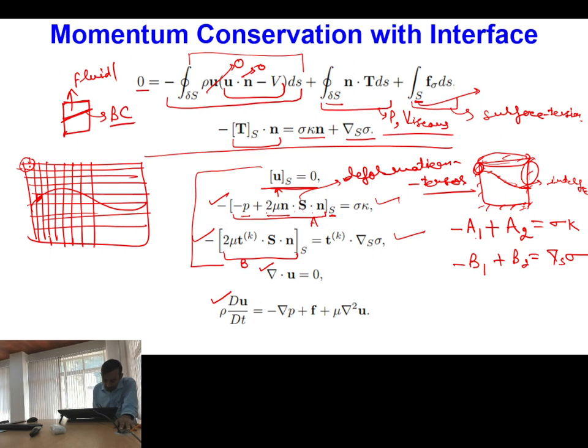Similarly, for fluid 2 you can solve this entire portion, but whenever you come to this cell, you will be solving only this much portion, and then at this point also you will be treating these equations for fluid 2 as boundary conditions. Is this point clear? So these boundary conditions are common for the interface between fluid 1 and fluid 2. This is how your two fluids are coupled together.